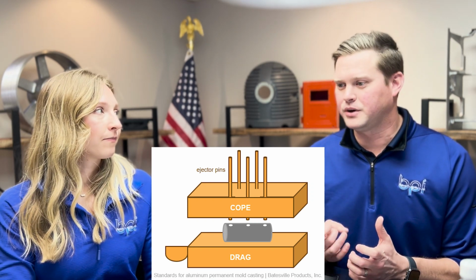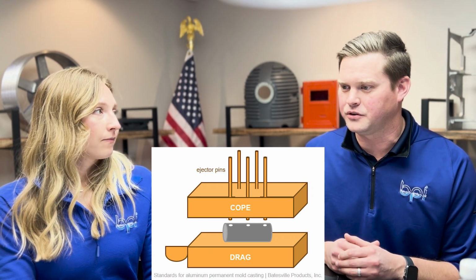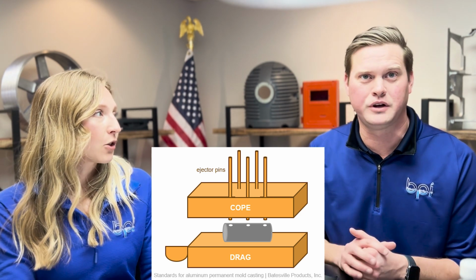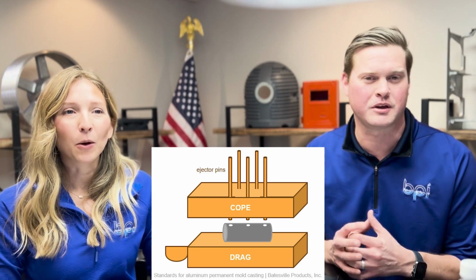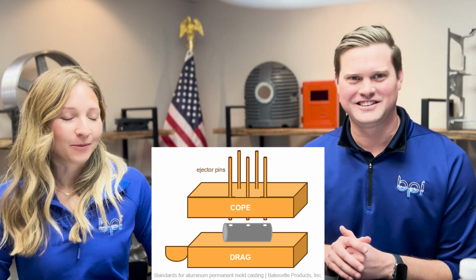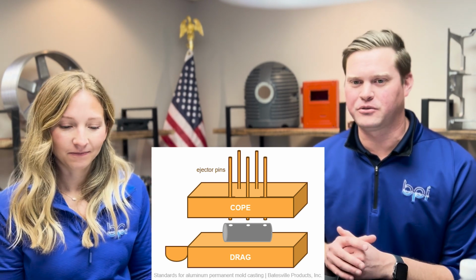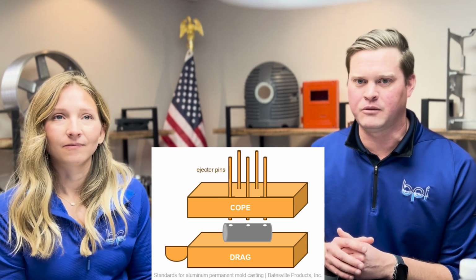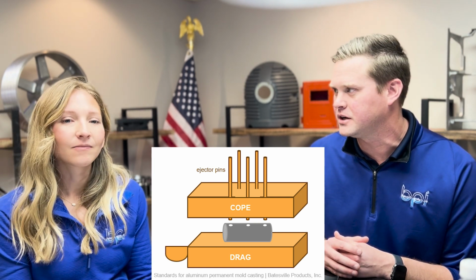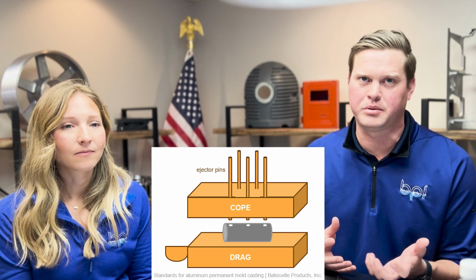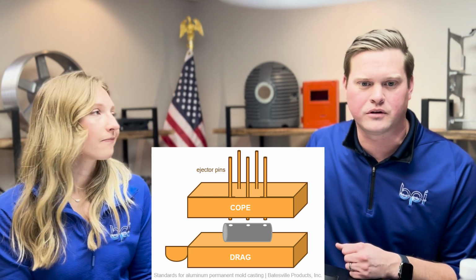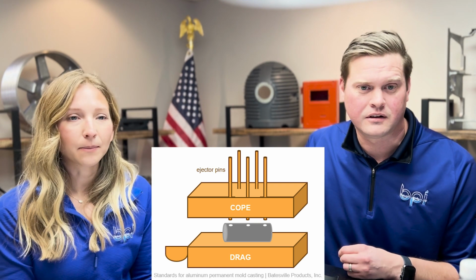You could, if you put an ejector pin mark on a really small surface area too, you could end up shooting it up into the casting, and that's something. Poke a hole. Exactly. Better way to say it. Unintentional core hole. Yep. So that's something you definitely want to look at. And again, we work very interactively with our clients to make sure that we work that type of stuff out, or really try to pinpoint where we might see some of those issues, and try to design it out before the mold's even cut. Yep.